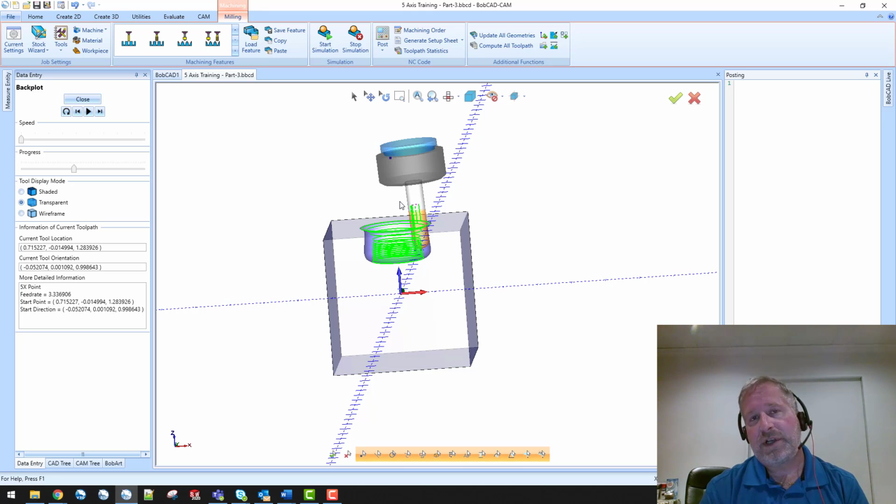For those of you that are on table machines and things like that, you have to be aware of what the travel limits are on your table and on your machine. And sometimes manipulating that point and getting it in the right place is going to determine whether you have an over travel because of the tool path that you're creating. Once you go to post-process it, you'll get an over travel. Or if you have the point positioned right, it could keep you from having an over travel, yet you can still reach all of the regions of the part.